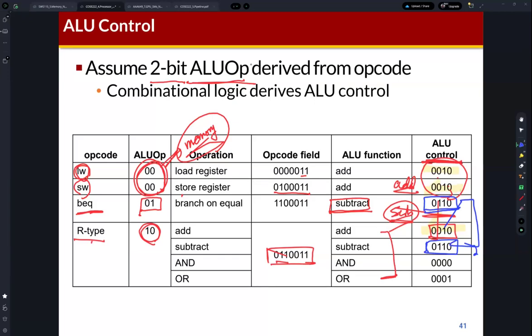Okay. So we can just define these ALU control signals firstly based on the type, the class of instruction, and then if the class of instruction is an R-type instruction, we need to check the other fields such as the function 3 or function 7 field. Okay.